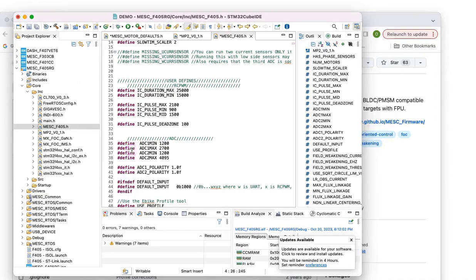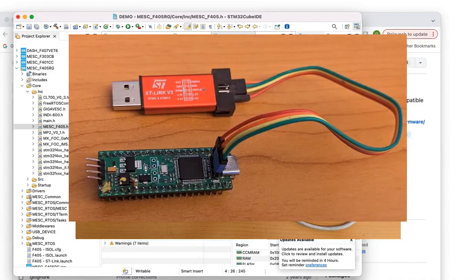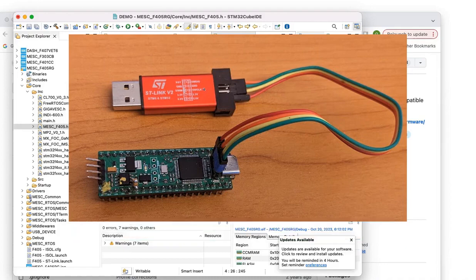Now we're going to connect the ST-Link to your computer and the pill. ST-Links are available from lots of different sources, and there are a lot of tutorials for using them to flash a pill. The idea here is that the ST-Link device is connected to your USB cord, the USB cord is connected to your computer, then these wires go from the ST-Link over to the pill. There's only 4 wires, and they're usually labeled with these names.